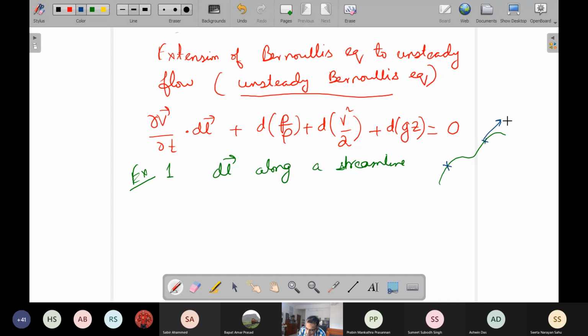It is defined by its unit tangent, or it is better to say streamwise coordinate, which is the local tangent, and the cross-streamwise coordinate, which we call maybe the normal. So you have a streamwise and a cross-streamwise coordinate. The velocity of flow is always along the streamwise coordinate of the streamline.